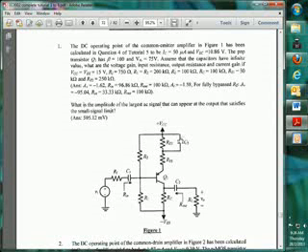So it's basically a short for AC. So all these capacitors C1, C2, C3 are all shorted for AC analysis. For AC analysis, another important thing is that the DC sources, which is this and this, are both grounded, connected to ground, 0 volt. With that, you'll be able to get the following figure.